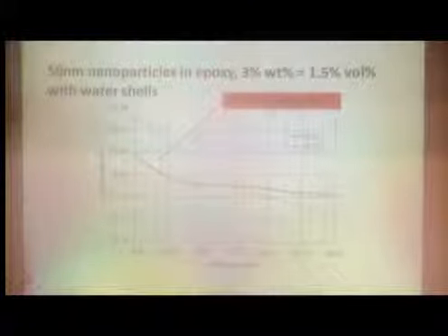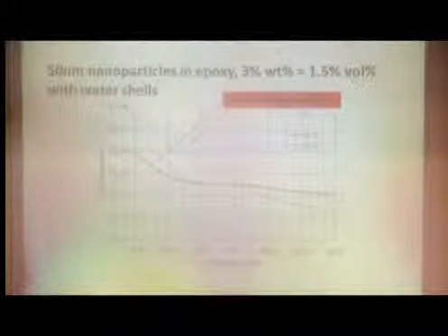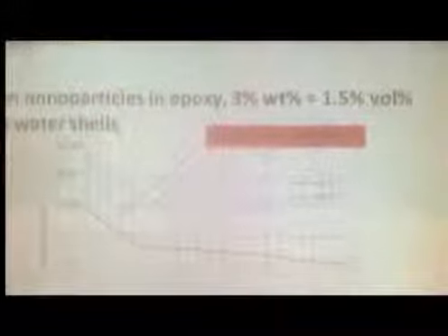And indeed, if we look at the dielectric properties of the first system, the 3% weight one, where we have limited, we're below the percolation limit, we actually do see quasi-DC with parallel slopes on these Bode plots of real and imaginary capacitance at low frequency. If we silanate that, however, we don't see that anymore.